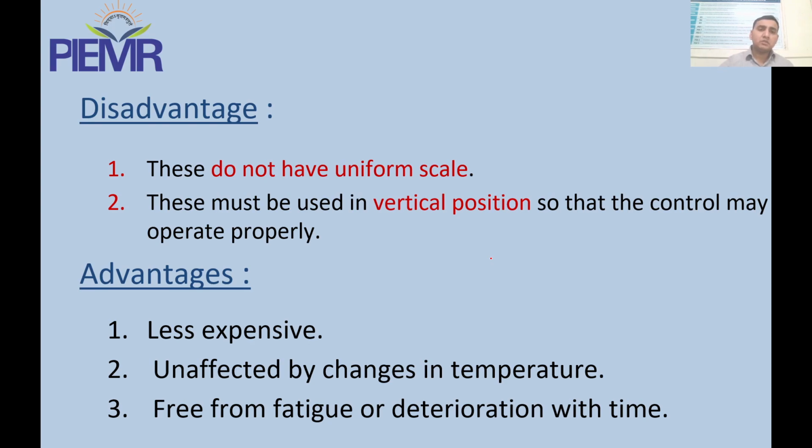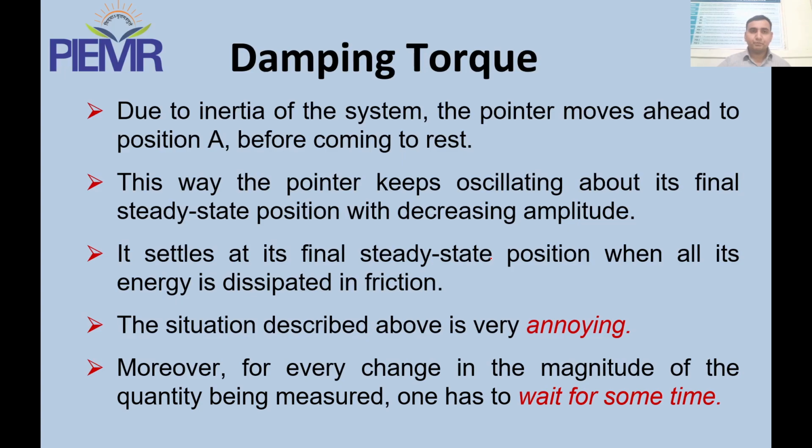Now the advantages. Unlike a spring, you do not have to calibrate it every time, and the controlling mechanism is not changed by temperature. It is free from fatigue, and most importantly, it is less expensive than spring control.